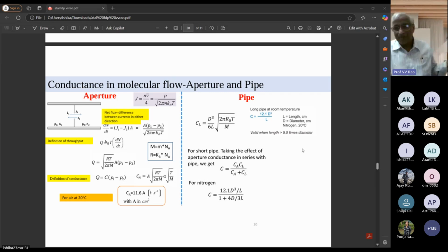After all, your chamber is also a pipe, welded, etc. It is like 1 meter dia, 3 meter dia. If the connecting pipe is also 1 meter dia, then there is no meaning. Your volume will increase like anything. Dead volume increasing. Yesterday he was telling about the thin film deposition unit. The volume of the chamber should be as small as possible, so that the consumption of costly gases will be less, and the maintenance of vacuum is also very good in deposition units.